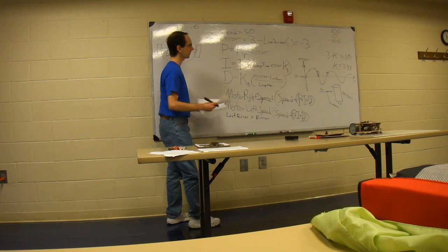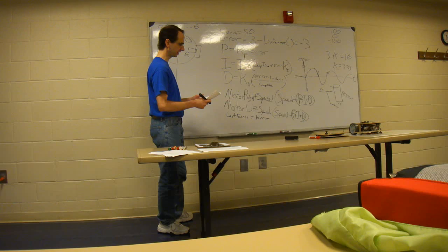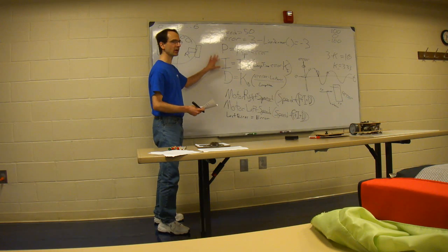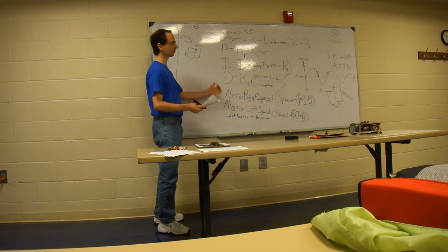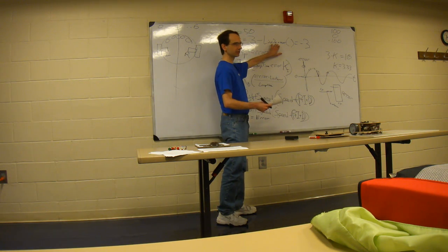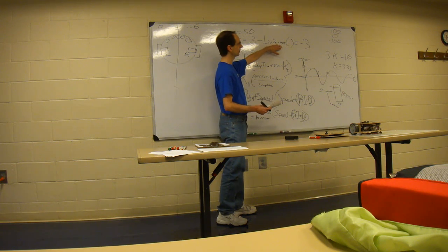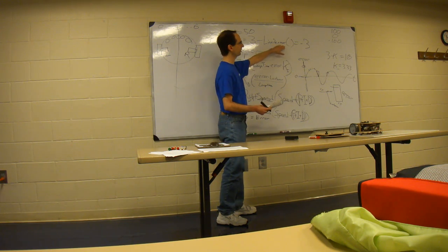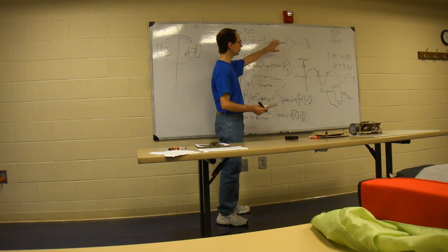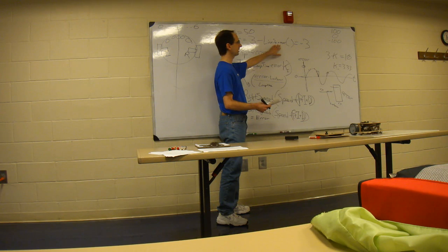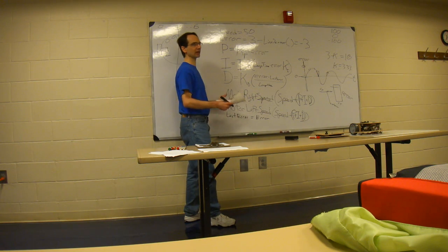So now I'm just going to talk about some general gotchas, some devils in the details kind of thing. For one thing, PID is not a filter. You have to do all your filtering before you get into your PID loop. In other words, in the call that you're making to your sensor. In this case, we're making a call to a line sensor. This could be your call to your temperature sensor. Whatever is feeding the data into this loop, that is where you have to be doing your filtering. Any error, any noise in the system, the PID loop is going to see as actual data.